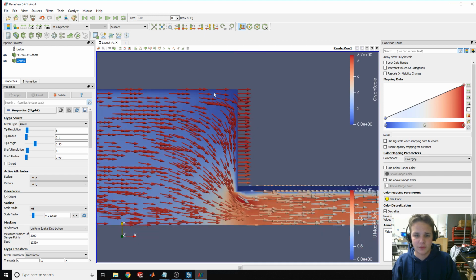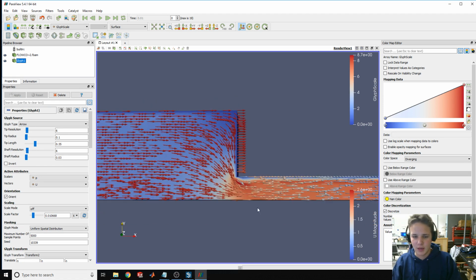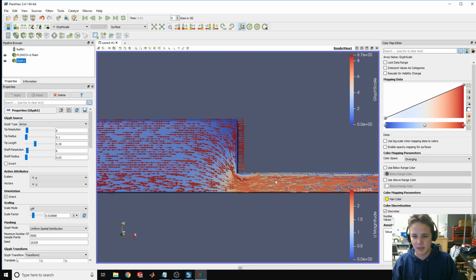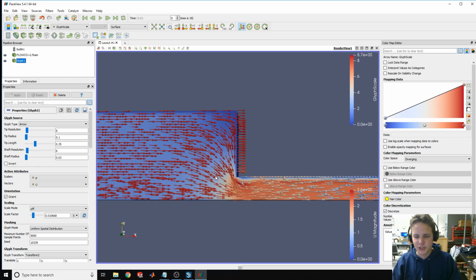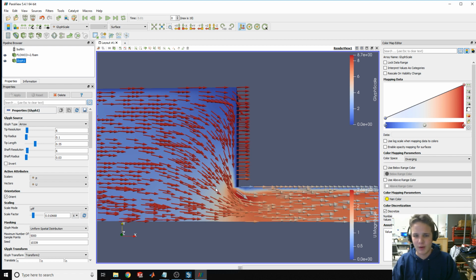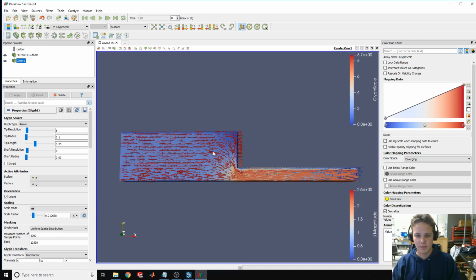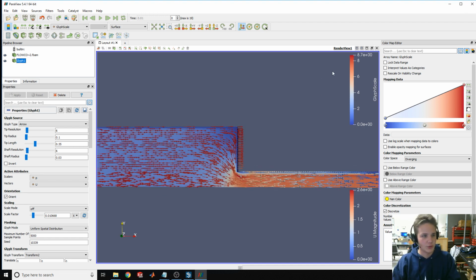So you can see that all this flow is coming in. It's doing that radial convergence, converging into the smaller area, and then you can see it speed up and basically get pretty straight around right here. But you can still see those angles here. So yeah, with a finer mesh, it can be more accurate, and I also can show you a little more of where each flow is, because if I had, say, a tenth of these, I might not even have a vector here. So it might make sense to have a lot more vectors just to see at every spot in this geometry what direction the fluid is going. So that's basically what a finer mesh can create and can let the engineer or whoever's doing it see.